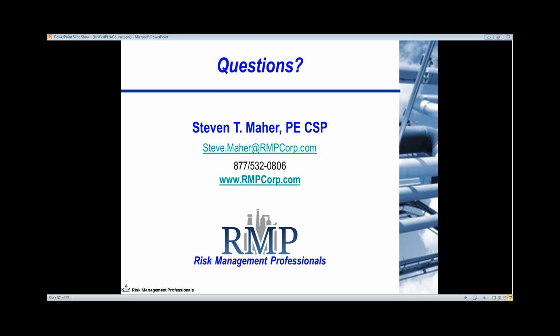And if you do that during session, our experience is it may add an extra 10 or 15% to the overall time of the study, but it also gives the team, especially for the high-risk scenarios or high-consequence scenarios, which are the ones you want to do LOPA for, a little bit more time to think. Doing the LOPA gives a little different perspective, a little bit more insight, and those are very valuable. And a lot of times, maybe 10% of the scenarios that we actually apply a LOPA to, there's some new insight or some new information or some new conclusion that can be drawn that's very valuable.